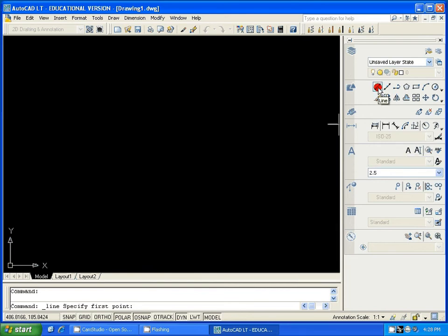line. Hover over your screen, and you'll notice that 3 boxes come up. These boxes allow you to put information in to draw geometry. And this is different from what you were doing before, where you'd put your information or input in the command bar and then go back up to your black model screen and draw your geometry. People like to do this because it is more efficient and you don't have to keep switching between the command